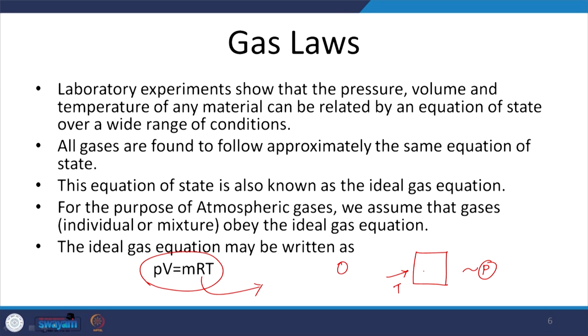Now, for this you can use this equation, but only if you know the specific gas constant of oxygen to be used here. That means every gas follows the same form of ideal gas equation, but it will take a different gas constant for each gas or for each gas mixture, right.